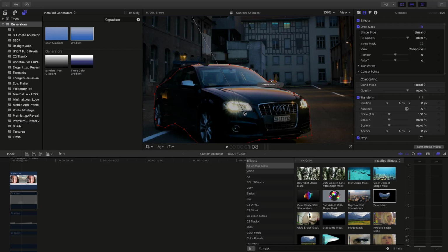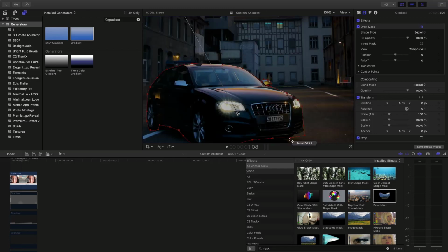So I need more sensitive adjustment. I hold the Command key to use Bezier and drag the mouse to make these angles more curved and make smoother lines in the shape of our object. I think I can make less adjustments in the bottom part of the car, because when I make the camera animation, it will be quickly covered by angle cutting. I think only contrast zones will be important in this case.